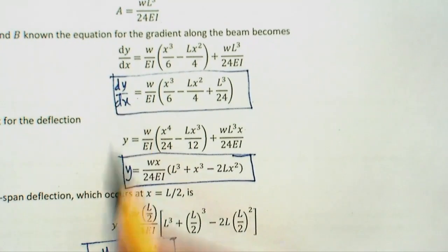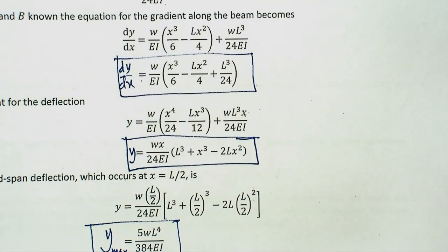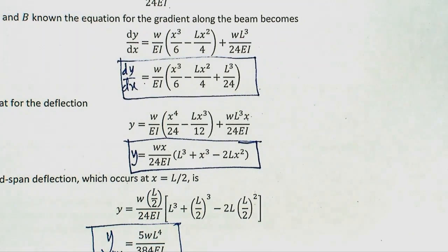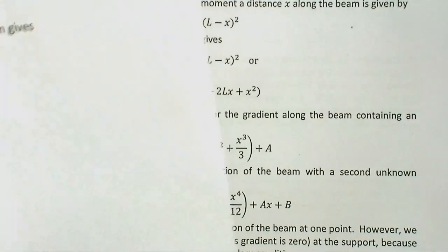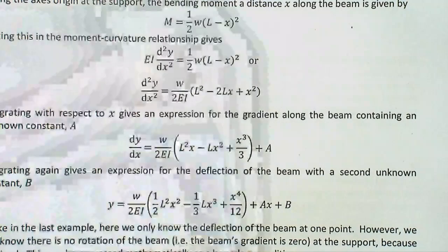And that will complete my expressions of deflection and rotations, and then once I plot it, I can find out what the maximum is and at which point it would be maximum, etc. So, these are the steps or process that we use to calculate deflection of a beam. Things would be a little bit more complicated, but the process is the same.